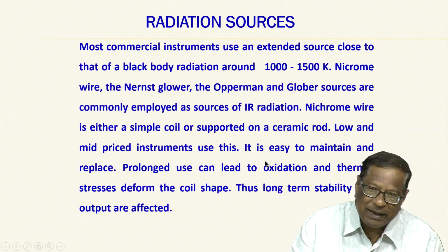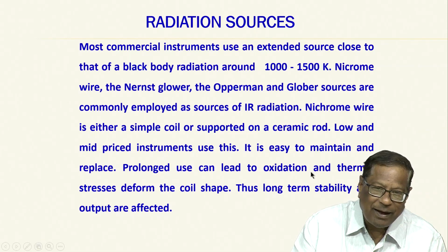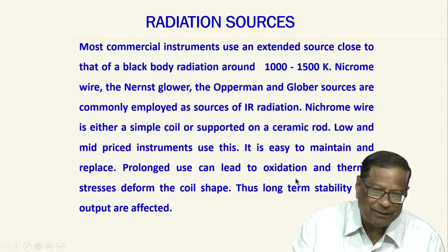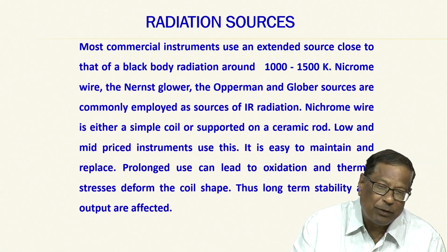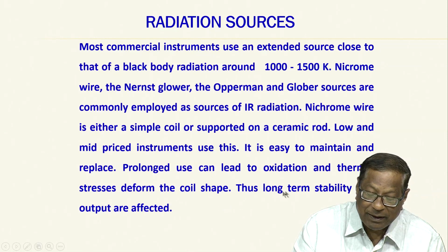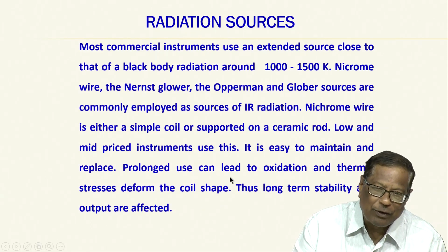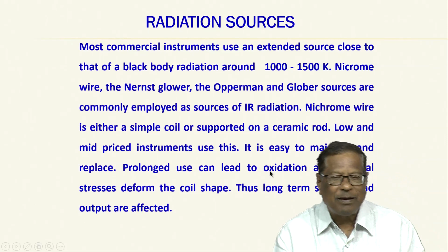Prolonged use can lead to oxidation. Sometimes the wire gets oxidized to oxide, and oxides are not good conductors of heat and electricity. So, you have to heat it more and more to make it look red, and the more you heat it, the more oxide will form, the less heated it will be. At some point a breaking point will be reached, and then thermal stress deforms the coil shape, and quite often it breaks into two. The connection is gone. So, the long term stability and output are affected over prolonged use.